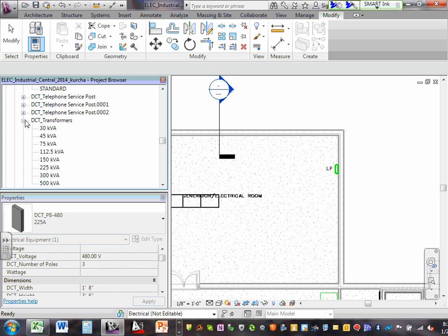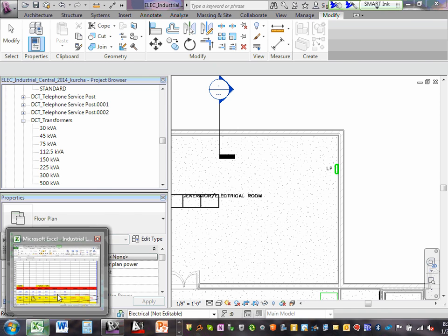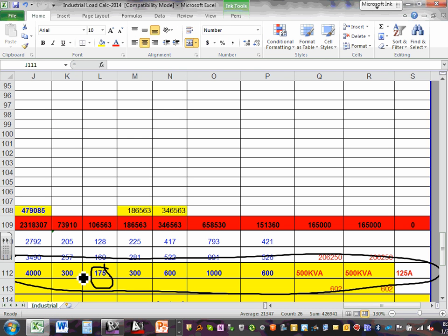Do you see where it says transformer, guys? Not utility transformer. Now I need to size my transformer. What size panel do we have? The size of my receptacle panel, guys, was it 300? Now, based on the size of the receptacle panel, I can size my transformer. We haven't done this calculation yet. I apologize. It's coming, guys. When you match a transformer to a panel, based on 300, there you go.